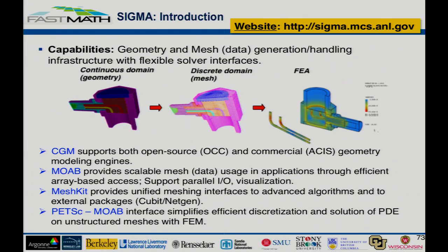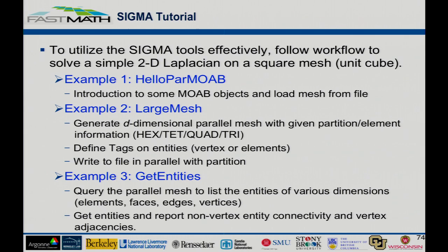And with the DMMOAB interface that I introduced earlier, you could use the MOAB mesh and then do your finite element based solvers. So there'll be 4 major examples. One is a parallel example, which is basically hello MOAB in parallel, where we'll load up a mesh and look at some of the base APIs, how to create the data structures and the different options to load a mesh file in different formats. It'll also include some querying information for different types of entities and of different dimensions and tag values.